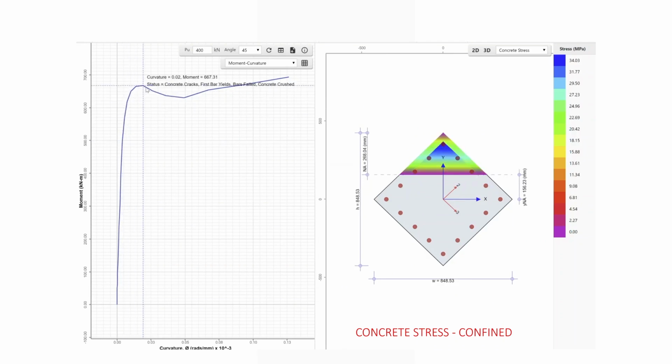So you will not get the same moment curvature capacity as on the 0 degree or 90 degree. And then you can see here, the cover is gone and only core is left. So the cover will be gone very quickly because the corner is under large strain and large stress, and it's unconfined, so it will just go away. So at an angle, the cover will fall and then core will be left, but there is also a triangle. So you don't get a lot of capacity in curvature when you have biaxial bending.